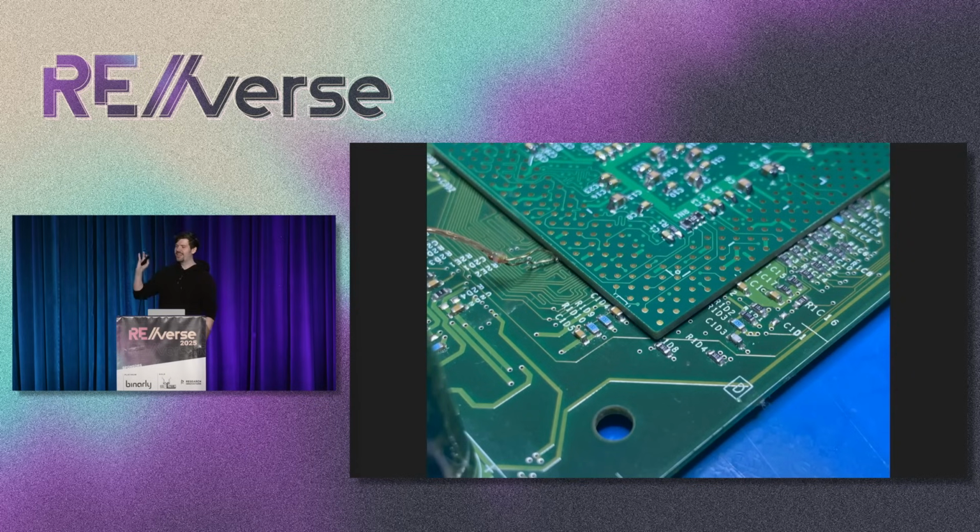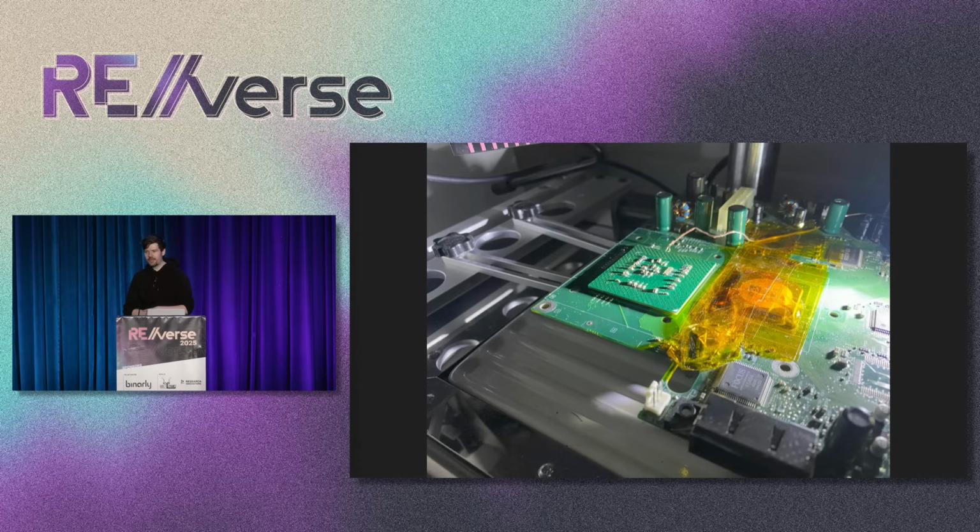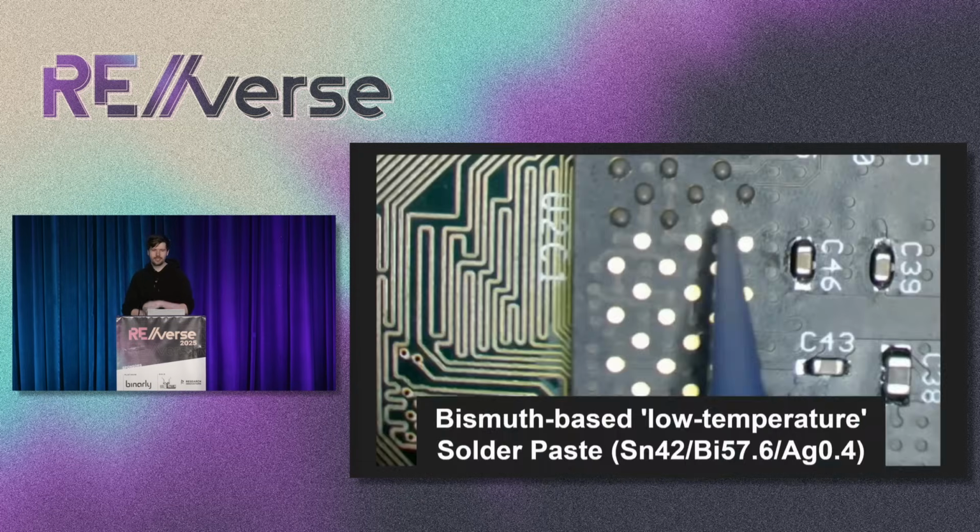But anyway, continuing. There's quite a bit of precision going into the design of the interposer. If you look around the corners, there are these two little caps right next to it, that is sub-millimeter precision that I was having on both aligning the BGA pads and everything, as well as around components on the motherboard. Just seeing me laying out the interposer, it's like, oh, maybe that's not too bad, but there's this landscape that I also have to account for on the board. But you put it down, we put it back under the BGA station, we run it through a cycle, and we get the interposer attached.